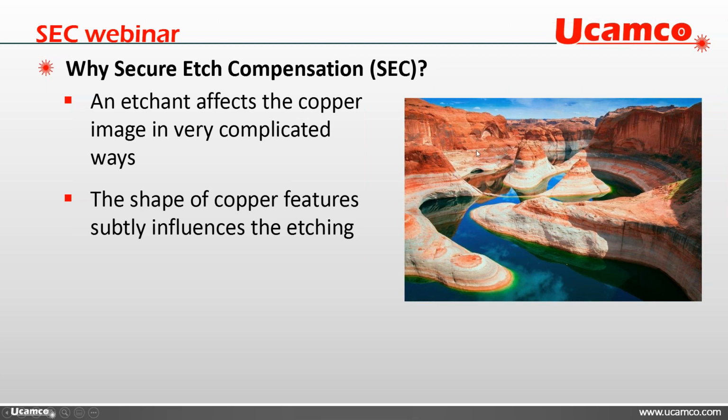They were getting etched away a little bit because you also have here a little foot on the bottom side. So that's why you compensate your etching, your image. And also the shape, how the image looks, influences how the result of the etching afterwards will look.